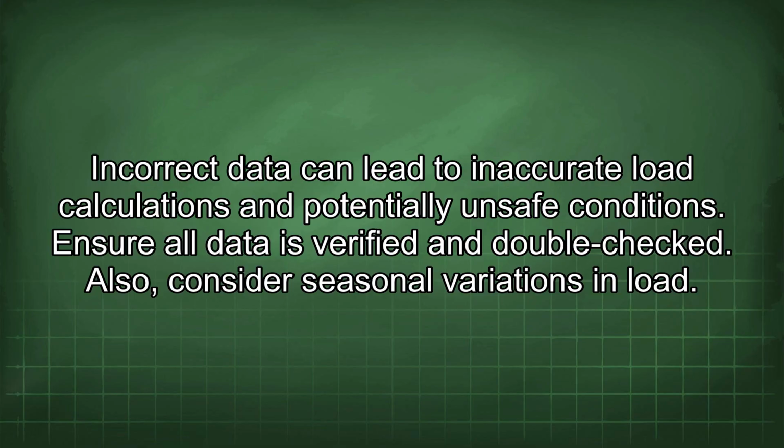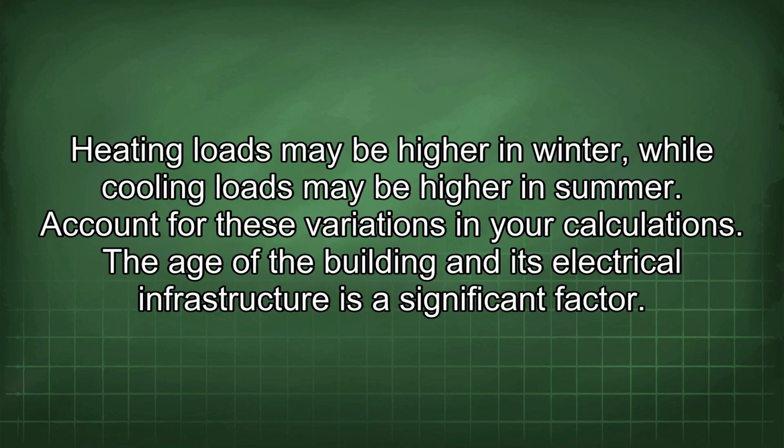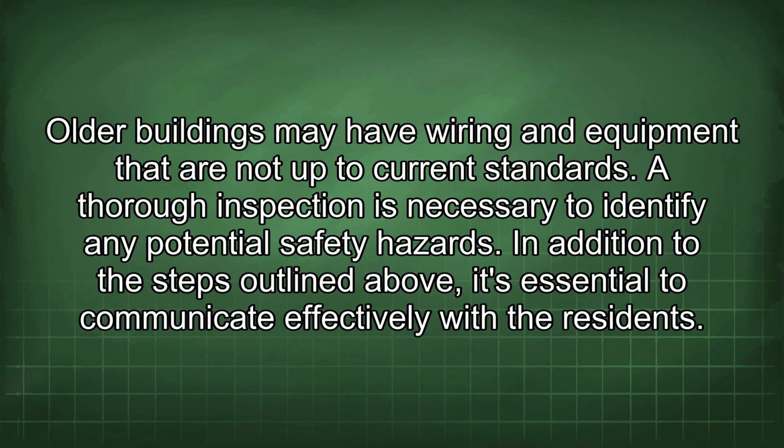Also, consider seasonal variations in load. Heating loads may be higher in winter, while cooling loads may be higher in summer. Account for these variations in your calculations. The age of the building and its electrical infrastructure is a significant factor. Older buildings may have wiring and equipment that are not up to current standards. A thorough inspection is necessary to identify any potential safety hazards.